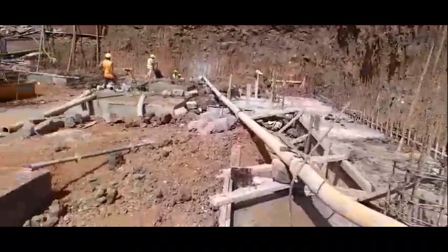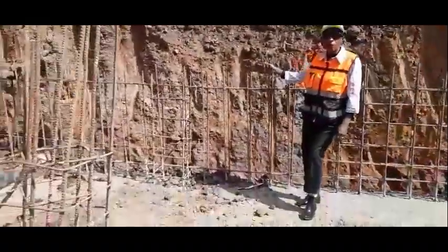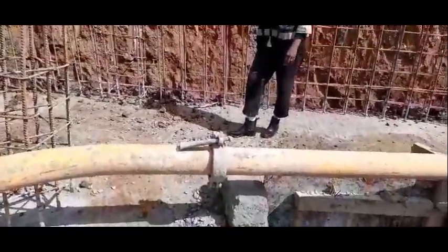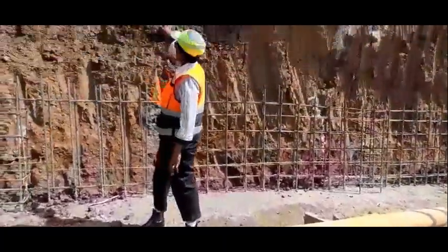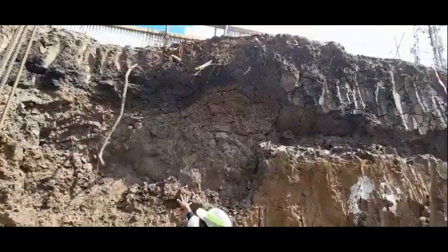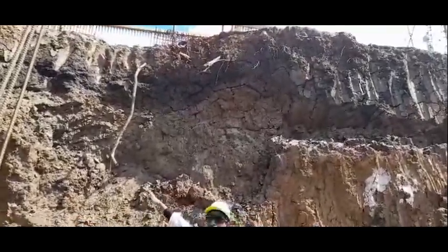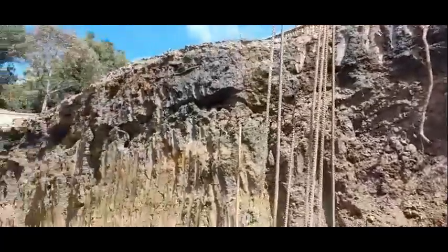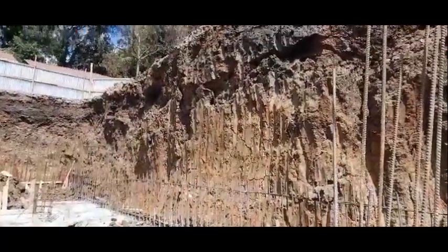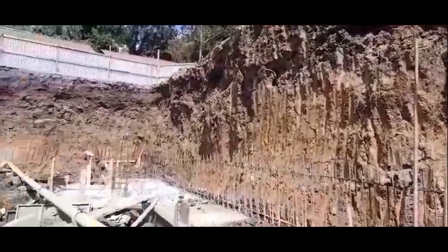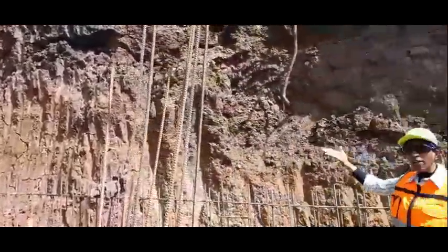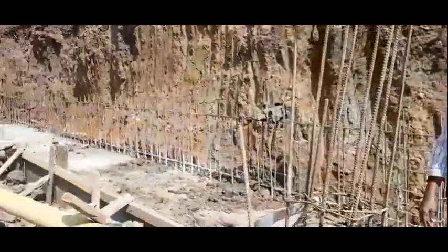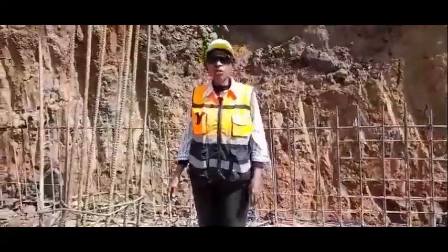If you look at this, this is part of the retaining wall, and where I'm standing is the footing. Behind me you can see a very unstable ground. When you hear of instability of slopes, this is what it means. When you cut unstable soil vertically, there is a danger of it collapsing. That's why you need to cut it at 45 degrees, especially if you have the space. So for now, let's keep watching.